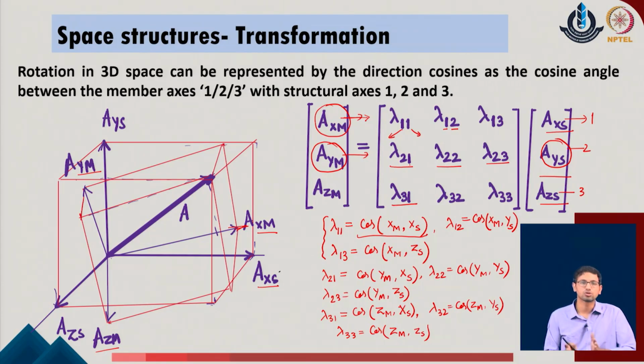The moment I get those components with respect to the unit value of the given vector will actually give me the direction cosines, the cosine angle with respect to the structural coordinate, x of m of the given system. Similarly, I can now do the similar process for the y m and z m in the given system.